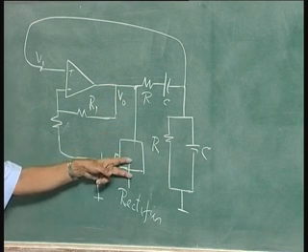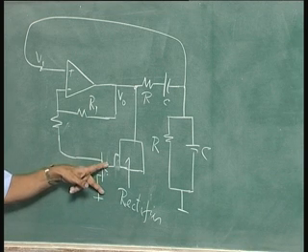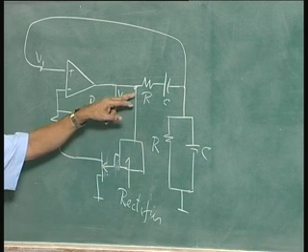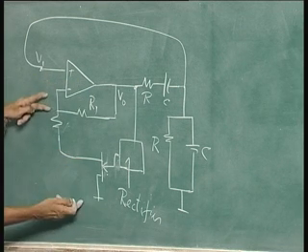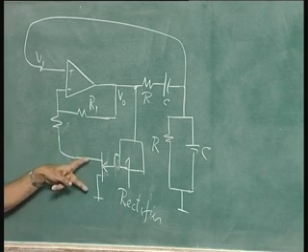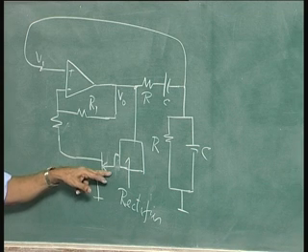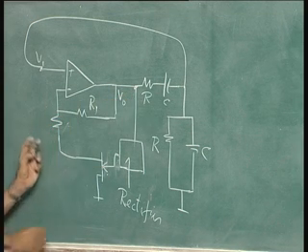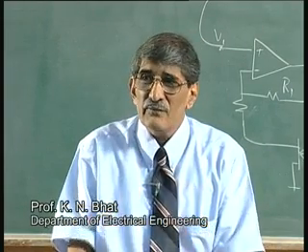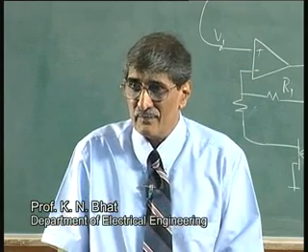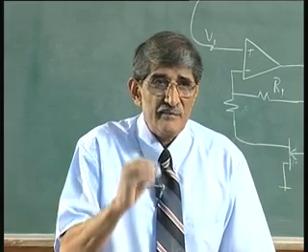So, a rectifier, and you can have an inverter if you like, so that the polarity is reversed and you can adjust that voltage. What this voltage is depends on what the voltage here is, and only when it becomes 0.5 k, in this example where I have taken 2 k, 1 k. So, this becomes half k only for a particular gate voltage, decided by the output voltage. I am sure some of you must have done this experiment in the laboratory. Only for a particular output voltage does it have a gain of 3. That means it will work as an oscillator with a fixed amplitude, a stabilized Wien Bridge oscillator.